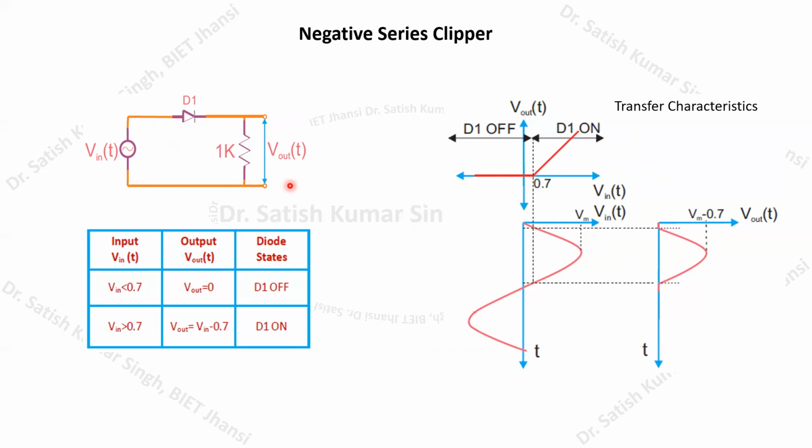But once it crosses 0.7 volt, you know that the current in the diode rises exponentially. So a huge amount of current starts flowing after 0.7 volt, and you can find that the voltage drop across this resistance will be increasing linearly. Okay, so this is its curve. It will keep increasing linearly whenever the input voltage is greater than 0.7 volt.